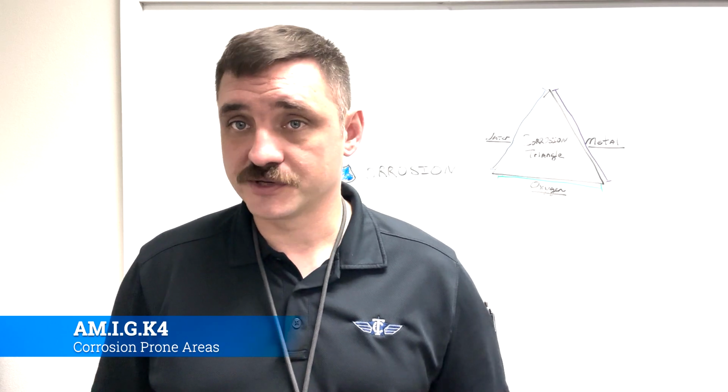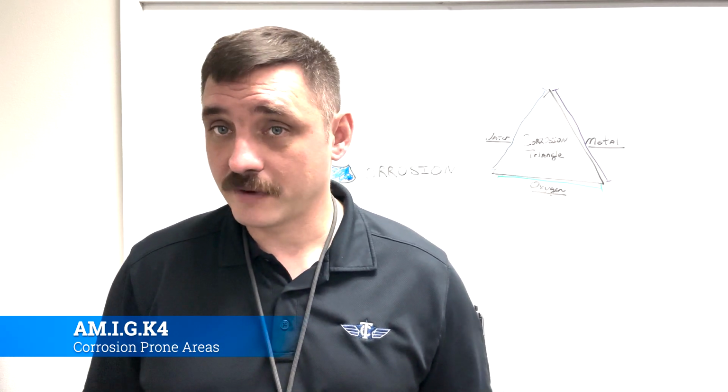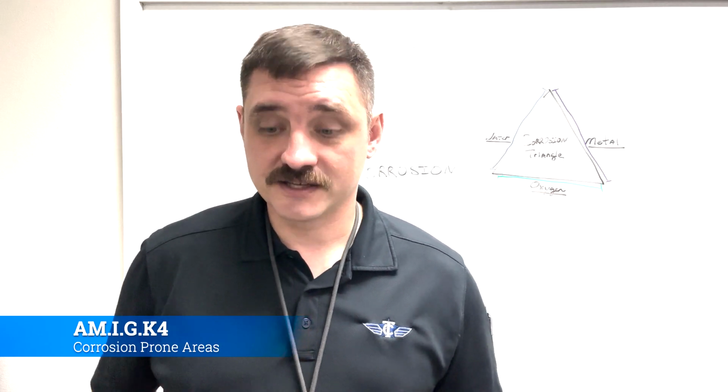Okay, battery compartments and battery vent openings. Old lead acid batteries, for sure, corrosion, 100%. I go to my airplane right now, and even though I have a sealed Concorde battery, if I pop open the battery box and look at it, I guarantee there's going to be some corrosion on the leads. It is every single time.